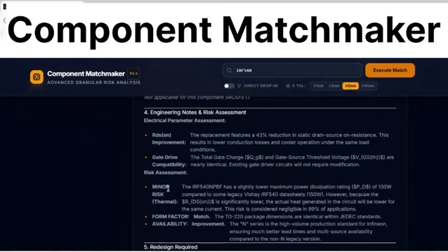So there is a minor change, as I mentioned. The lead-free version has a slightly lower maximum power dissipation rating, which is 130 watts compared to the legacy Vishay part, which as per the datasheet is 150 watts. Because the RDS value is significantly lower, the actual heat generated in the circuit will be lower for the same current. This risk is considered negligible in 99% of applications.